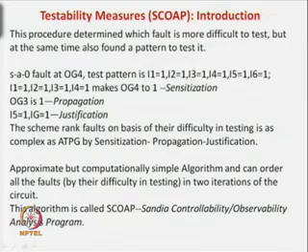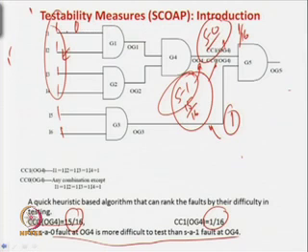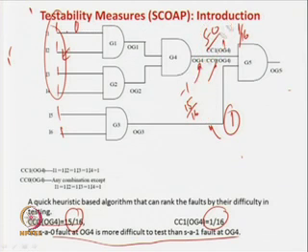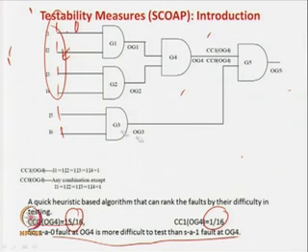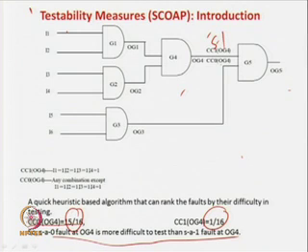So, this is not a very good approach. So, we have said that for the stuck at 0 fault the test pattern is all ones, and to find out which is easier or which is difficult to test fault we are applying all the patterns. For the stuck at 0 fault we have to apply a 1 over here.